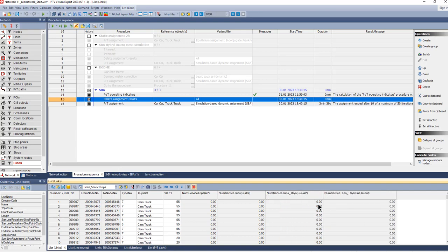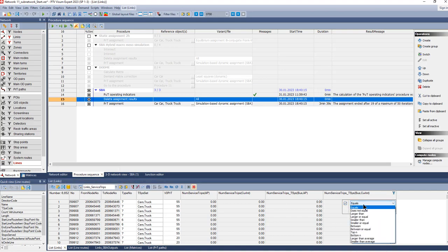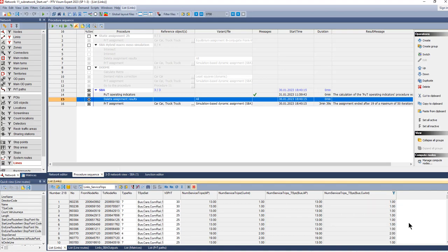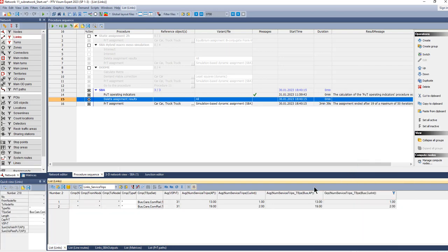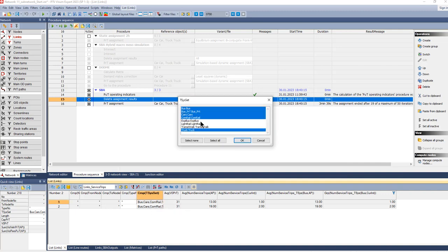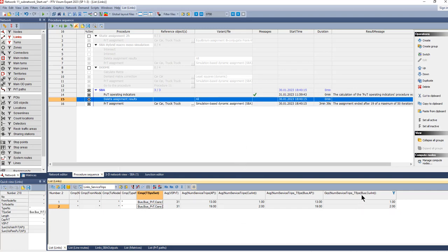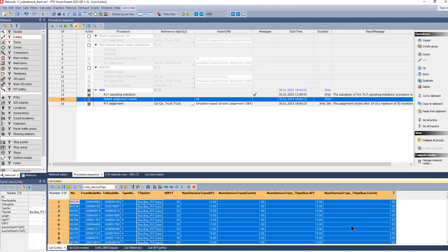And what we need to do is we need to open the link for the corresponding PRT transport system that we have generated, and in particular on those links where this base load applies. So we have this now filtered, and we can group that. And for those links, we add the private transport system that we have created so that we can simulate buses on the corresponding links.